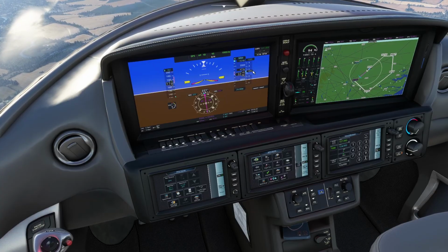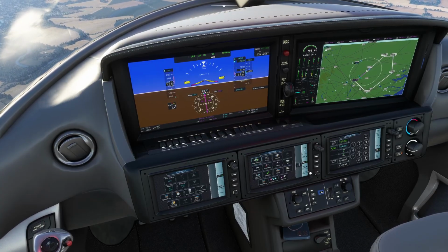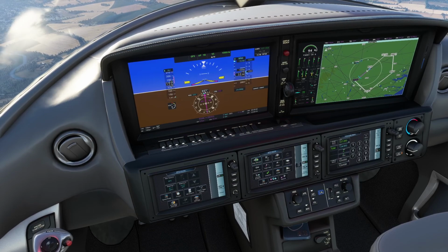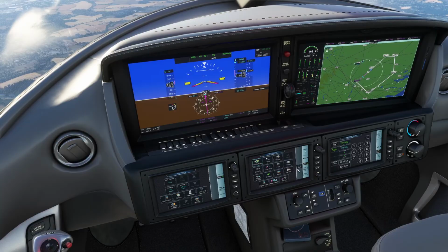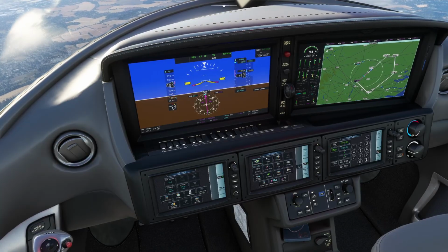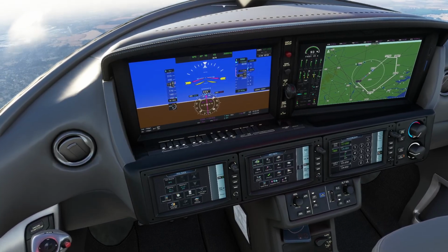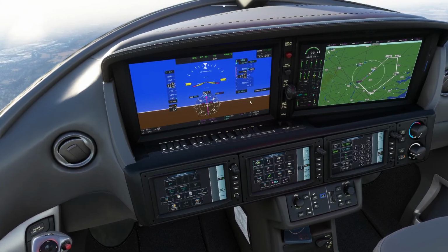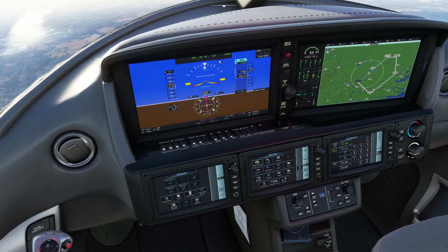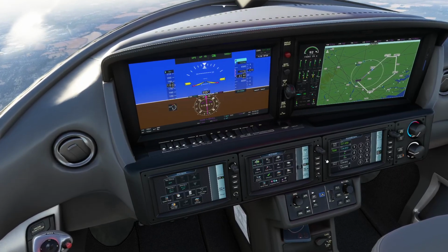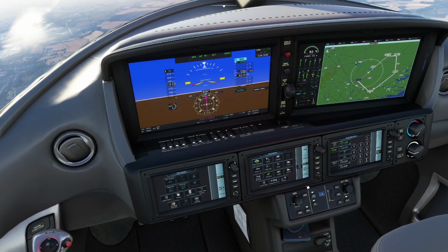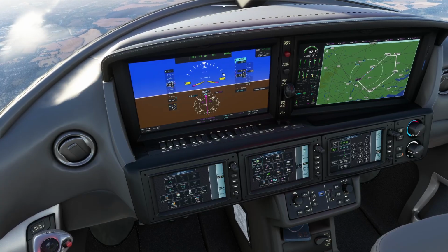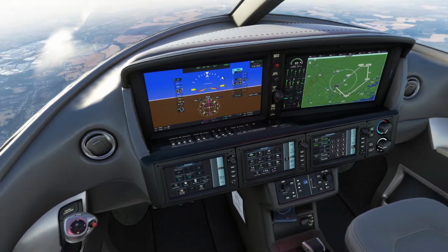So it's just settling down, and obviously you can see we are accelerating. So it will carry on accelerating. If we went for 2,000 feet a minute, it's just about accelerating still. But just as equally, we could go for 4,000 feet a minute to get there. Yeah, so I've set 4,000 on vertical speed mode. On the climb out, oh, it's already coming up to the target altitude, so it's leveling out. But the point I'm making here is vertical speed mode means you can select a vertical speed that the aircraft cannot sustain.